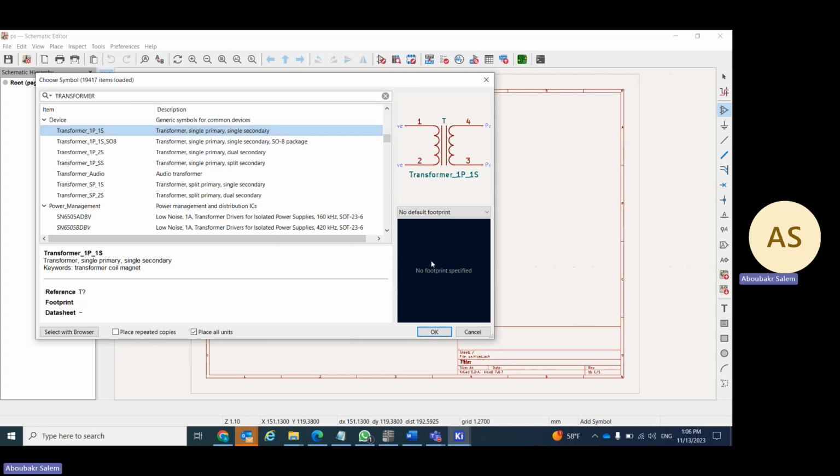But do you see any footprint for this transformer here? We don't have footprints, which means it's better to find a real transformer from the market and start using that in order to have the correct terminals, the correct size in case of footprint, and so on. So what we can do is, let's look for a transformer firstly on companies, suppliers of electronics, and grab this transformer and see if it is exists in our library or not. If it exists in the library, this is fine. If not, we need to add it to our library now. So let's see together how can we do that, guys.